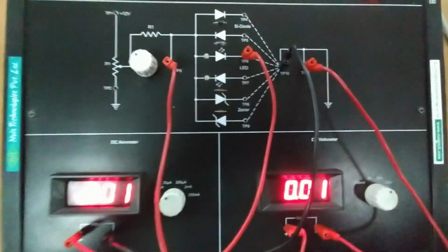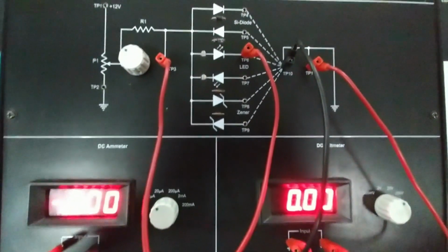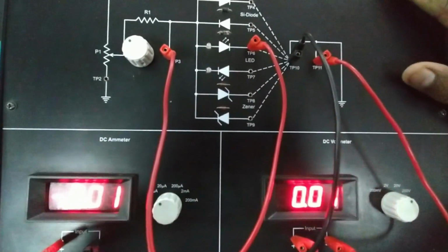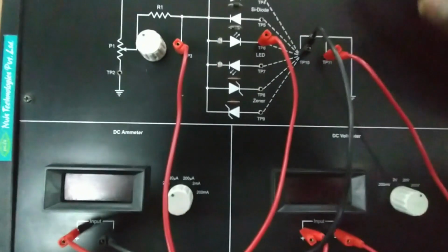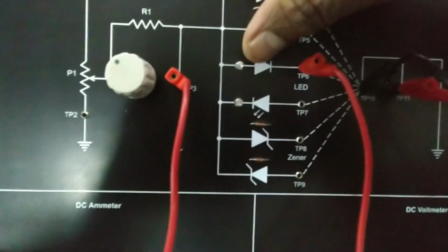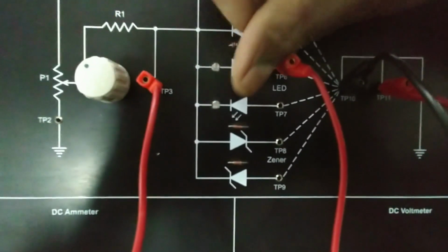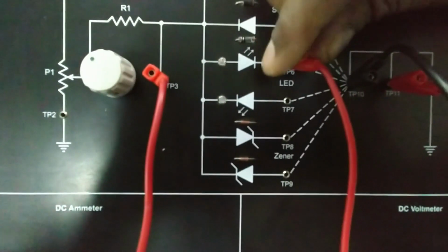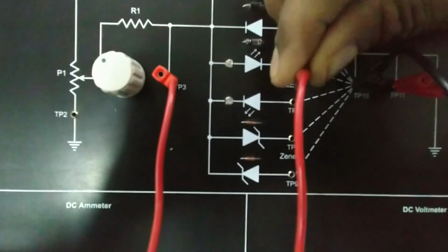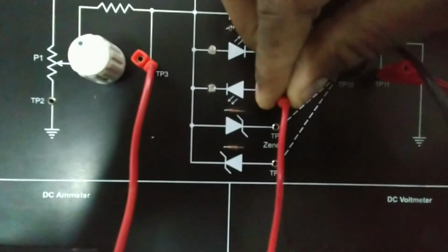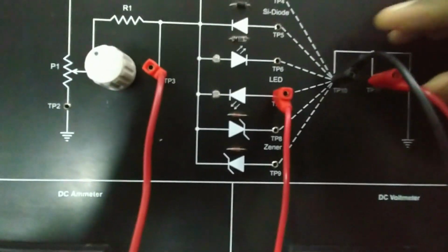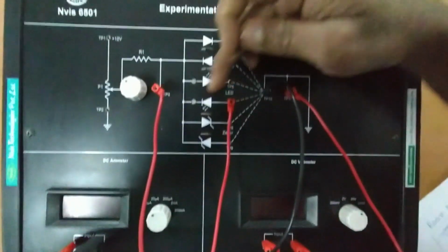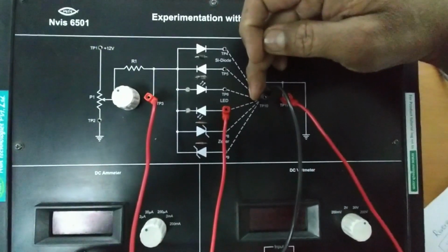Now I am doing an experiment for LED in reverse bias. First switch it off and you need to change the diode. Here the diode is in forward bias. The same LED is connected, but for reverse bias you need to change TP6 to TP7,